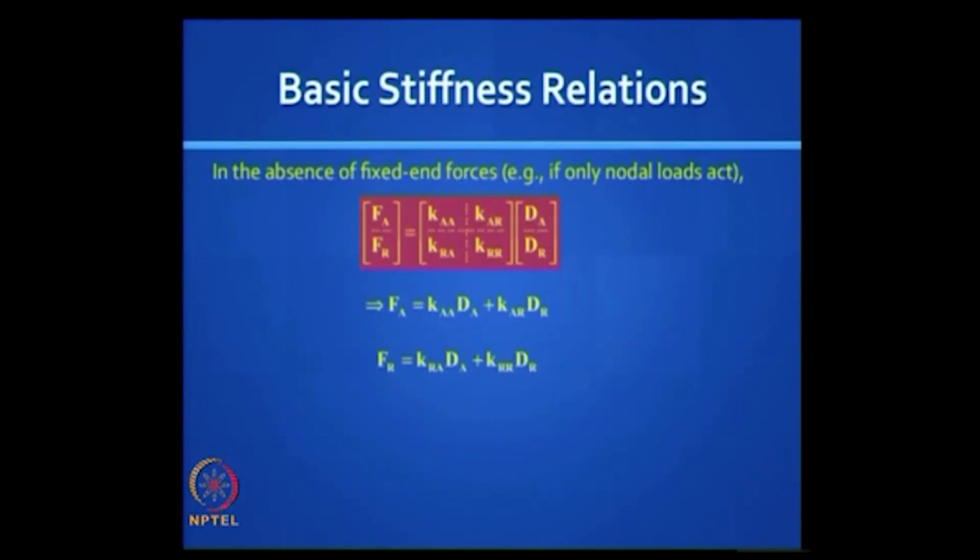But before that, let us say you have got the stiffness matrix, you can write relationships like this. Basically F is equal to KD at the structure level, but D itself is subdivided into active degrees of freedom which you do not know, dA displacements, but you know dr displacement, right, they are usually 0. On the left hand side, the force vector FA is known to you, that is a load vector acting at the active coordinates. FR is the reactions you do not know, right. So you can expand this into 2 equations, because the K matrix can be subdivided and they look like this.